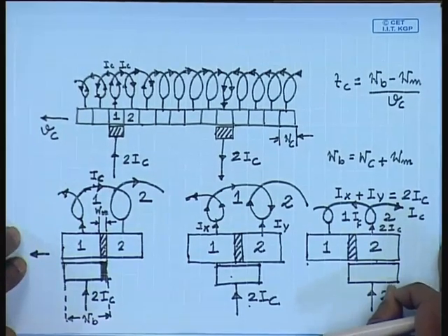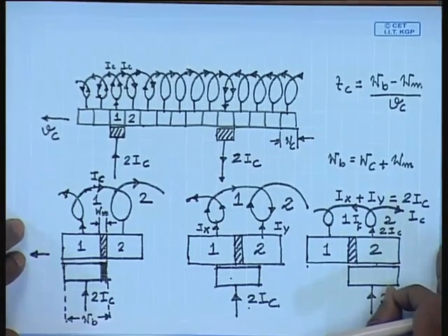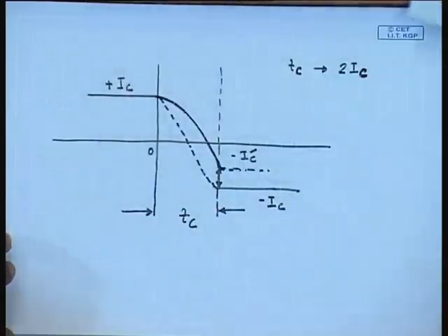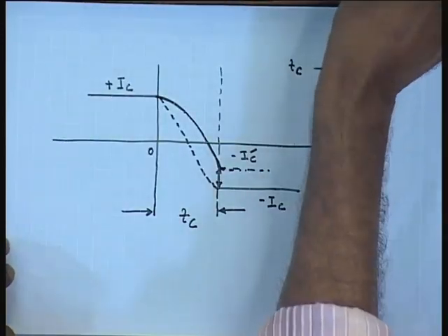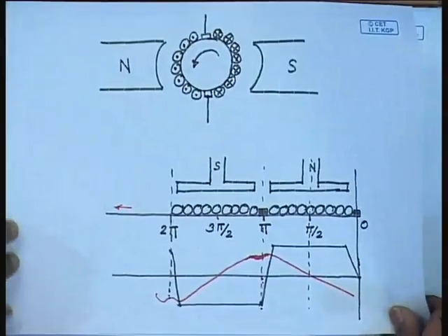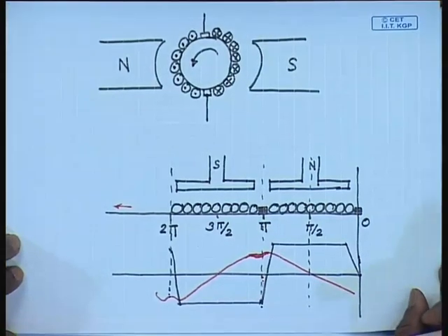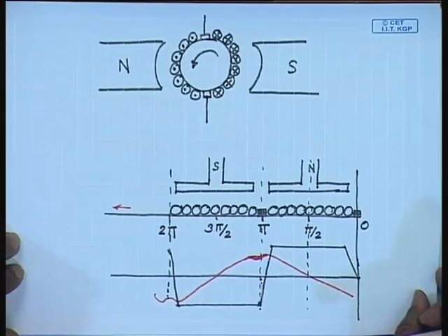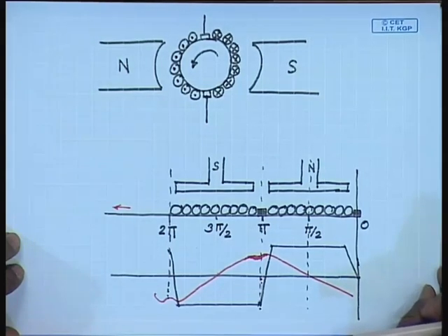Not only the leakage inductance of the coil, due to armature reaction, we have seen that the armature reaction flux leaves a residual flux at the interpolar axis, which is of the same polarity as the pole left behind in the generating mode.